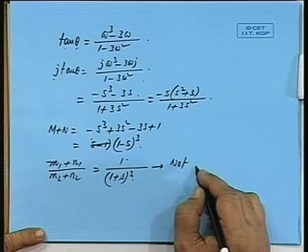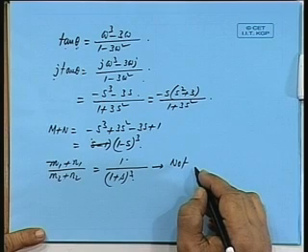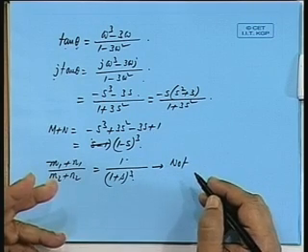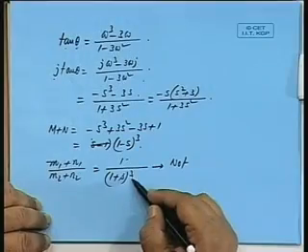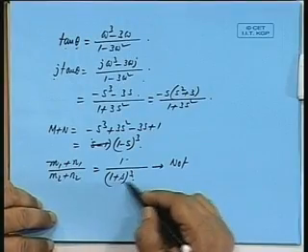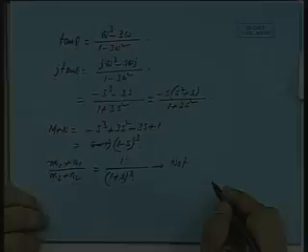Why is it so, the difference is 1 and the difference is greater than 1? Not greater than 1, it may or may not be 1. A transfer function is a ratio between two voltages, say, or voltage and current. So, that transfer function can be anything. It can have only one condition, the roots must be in the left half plane, that is poles must be in the left half plane. So, yes, this is a stable system.